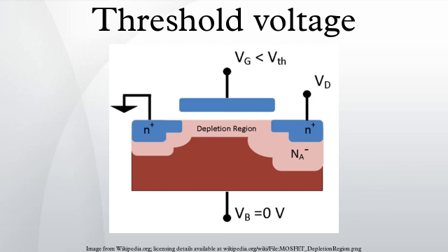If the gate voltage is above the threshold voltage, the transistor is turned on, due to there being many electrons in the channel at the oxide-silicon interface, creating a low-resistance channel where charge can flow from drain to source. For voltages significantly above the threshold, this situation is called strong inversion. The channel is tapered when Vd is greater than 0 because the voltage drop due to the current in the resistive channel reduces the oxide field supporting the channel as the drain is approached.